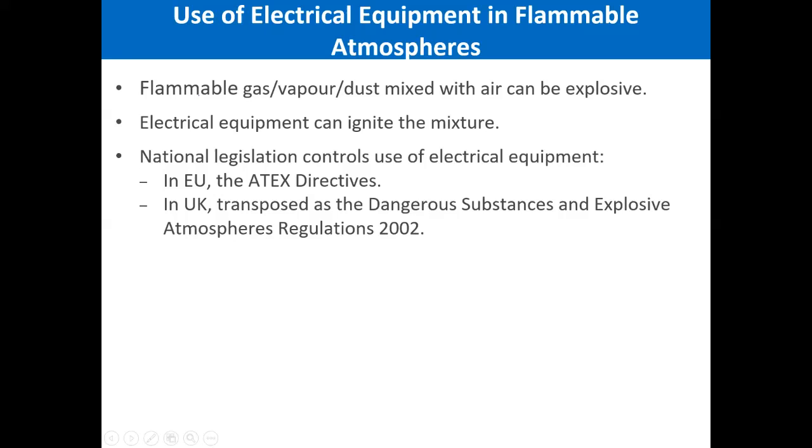So electrical equipment can ignite this mixture. Basically when there are loose connections, loose cables, they generate very, very small, very minor sparks. Sometimes those sparks are invisible, you cannot even see them. Sometimes that is enough energy from the electrical equipment to ignite a combustible mixture.